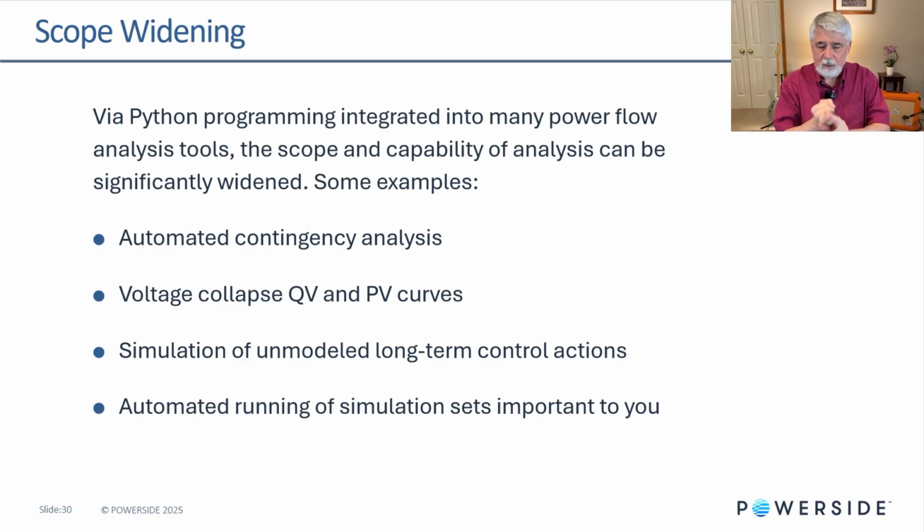You can write Python programs to generate these answers for you. The voltage collapse QV curves are a series of power flow solutions, one after the other, while changing and updating voltage and VAR conditions. How about simulation of unmodeled long-term control actions?